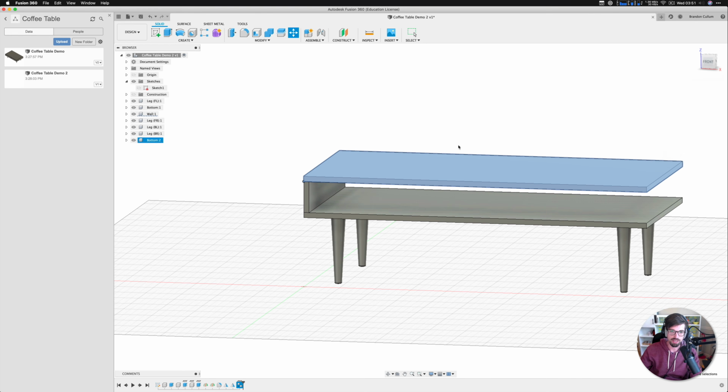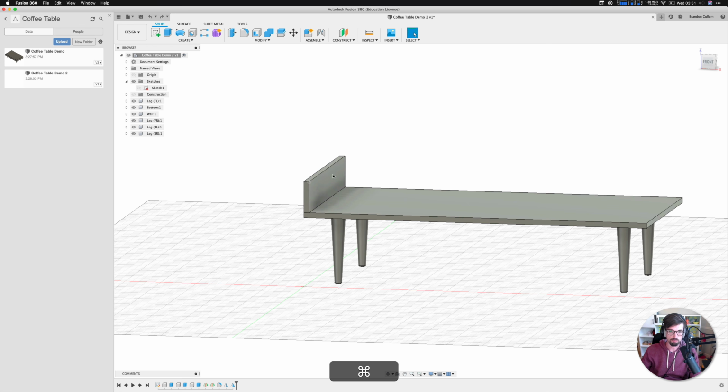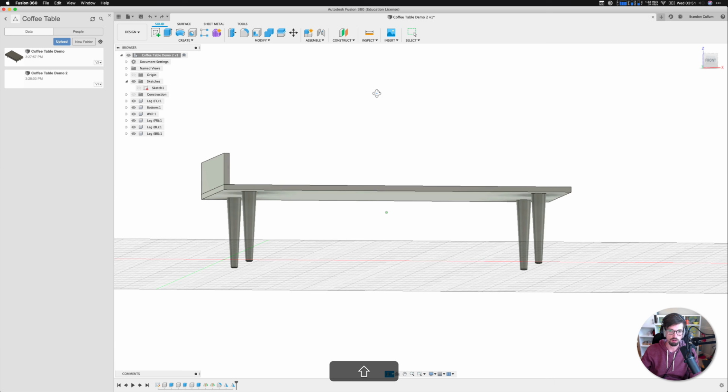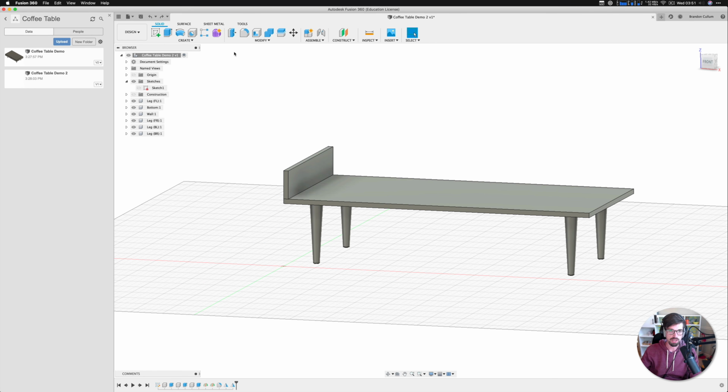So instead, let's delete that. What we're going to do is mirror again, which is usually the safest thing. So we're going to mirror this up. So we need another construction plane. Again, I'm on this guy. So we have these two, but we really need one cutting the middle of this.